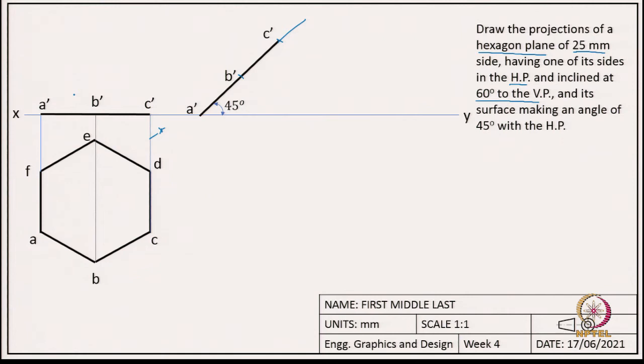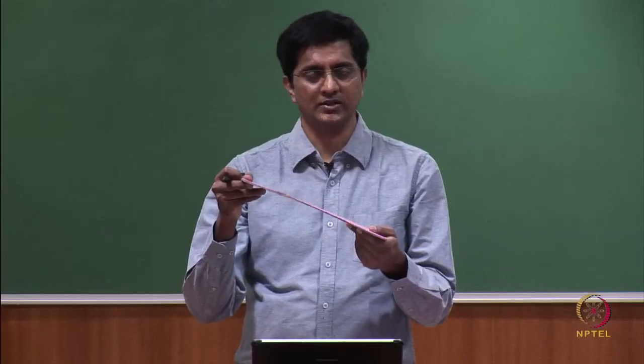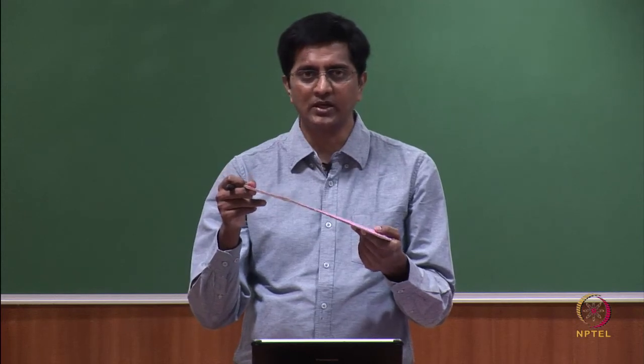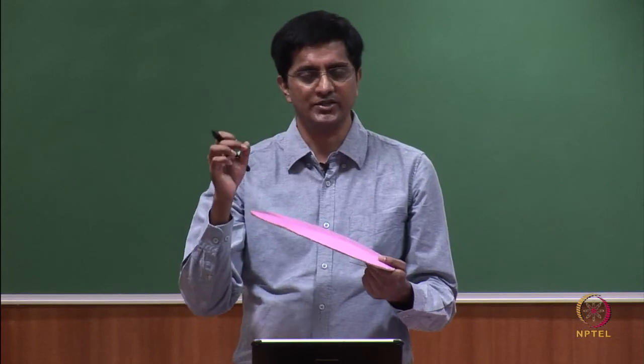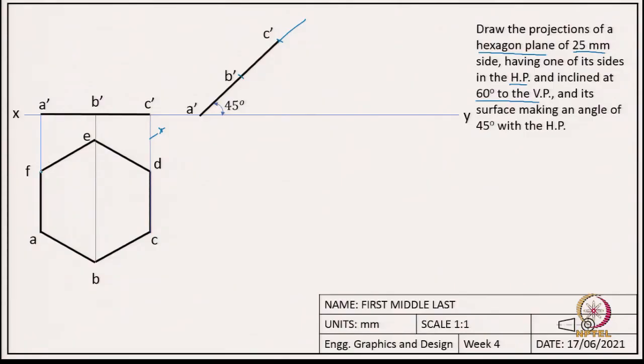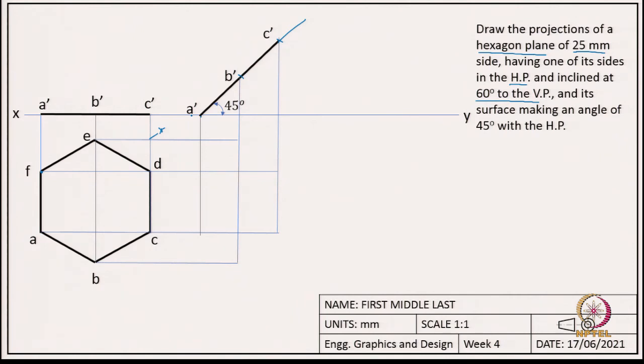Okay. So, once we know this, then how do we draw the top view of the hexagon? So, again the point is, it is very simple, you just need to trace the points. So, for example, this point F, you need to draw a projection line which is a horizontal line, and the similar point F which is somewhere here, you need to draw another projection line. So, we use projection lines from both the front view of step 2, let me write this, step 2, step 1.